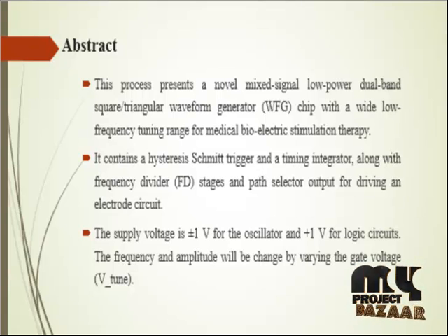It was fabricated using the GlobalFoundries 8RF-DM 130nm CMOS process. The supply voltage of the oscillator is plus or minus 12 volts, and the logic circuit is applied with a 1 volt power supply.